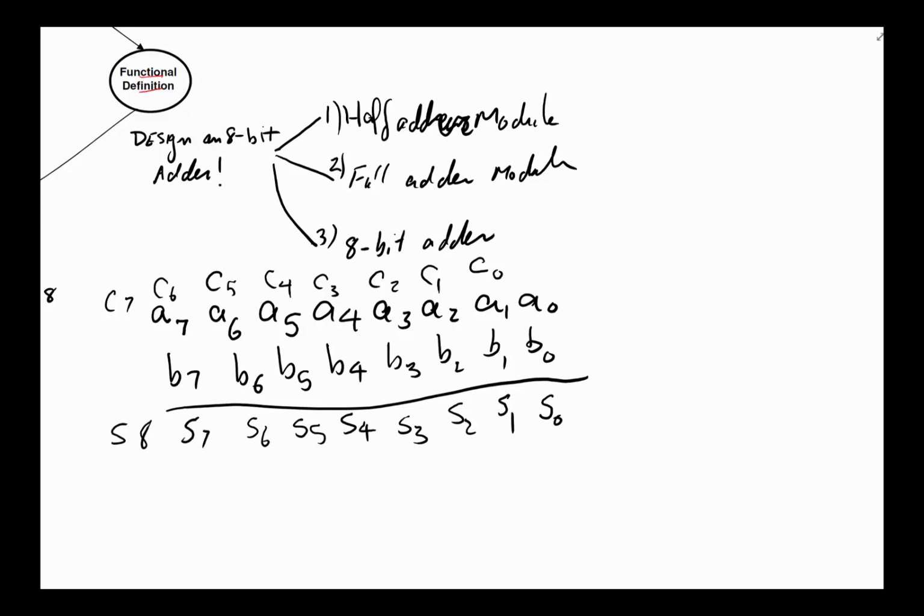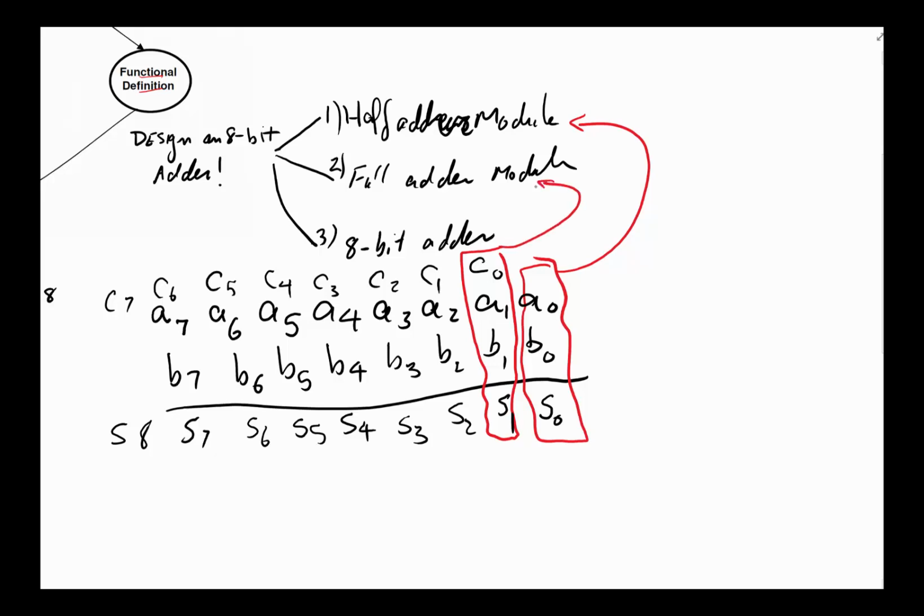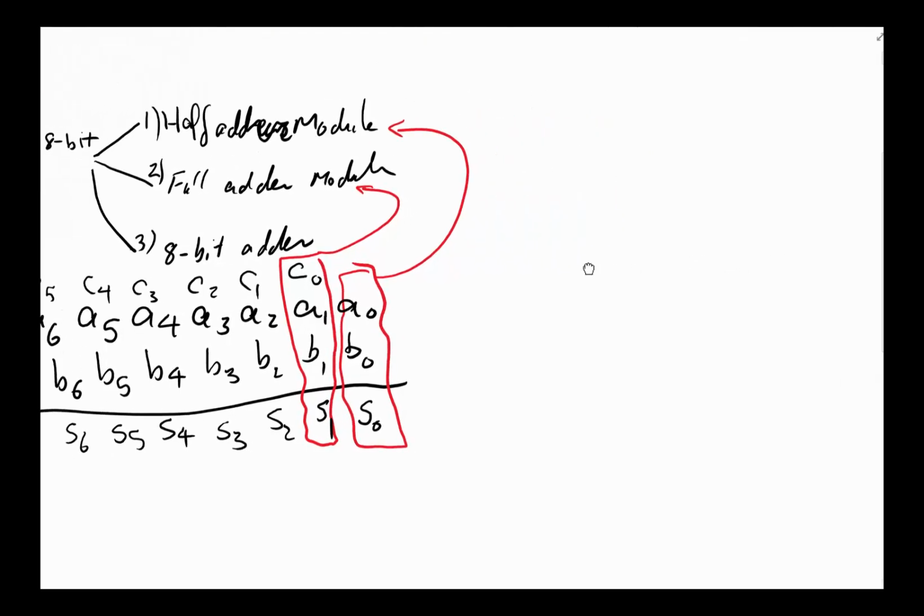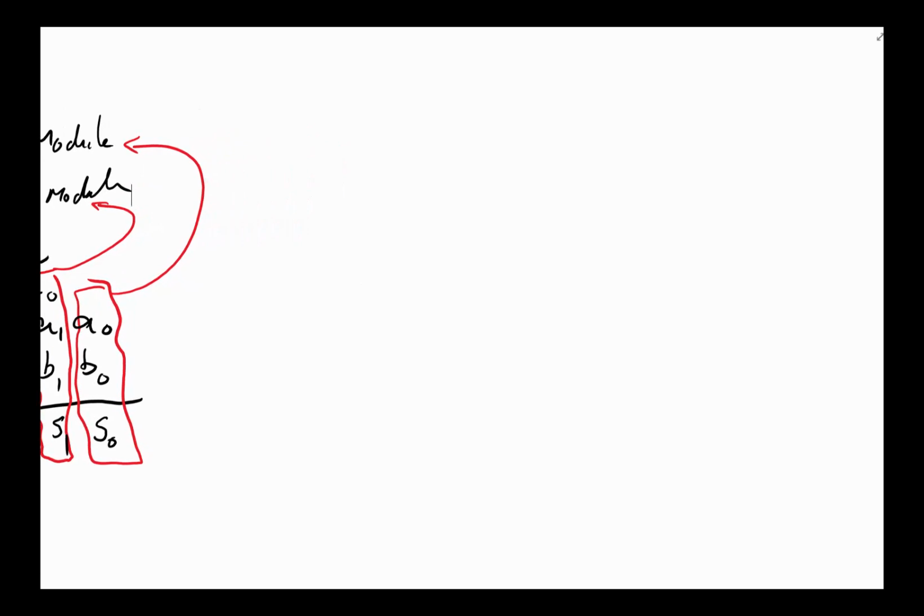So if you look at this operation, it is different than every other operation that is happening. This is the only one. The one that doesn't have a carry because it's the first digit is referred to as a half adder. The one that has a carry is called a full adder. So now that we hopefully understand why we're doing that, let's go ahead and try to design this.